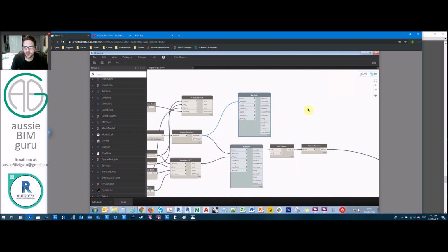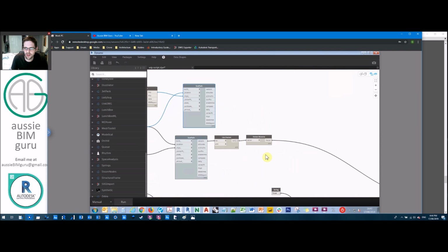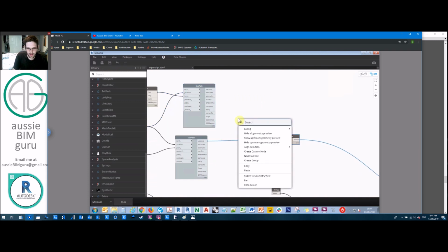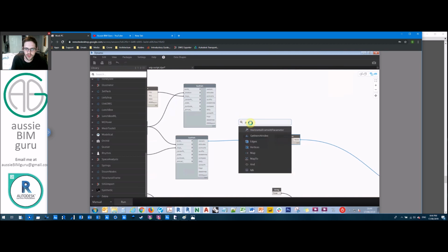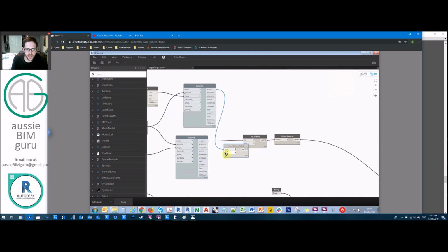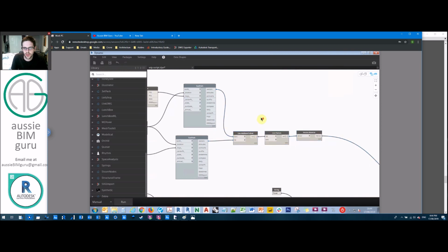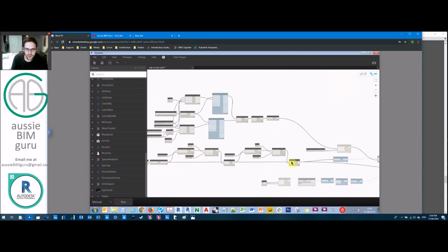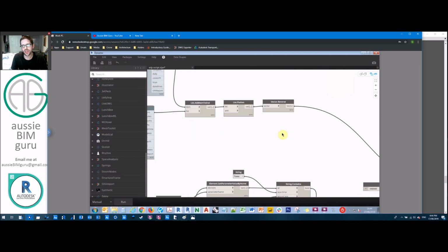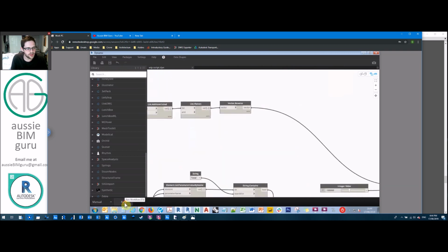After that, we need to add that item to the end of our vector list. I'll show you how that looks in a second once I've added the item. Sorry, my Dynamo is running a little bit slow today. Add item to end. So we want to add this vector to the end of this list, and then we flatten that list instead. Okay, so I'll run what we have to this point, which all that will happen now is it will collect all the sensors and it will collect all the vectors, and everything else is frozen currently. So if I run this, we should expect to see a list of all those vectors combined.